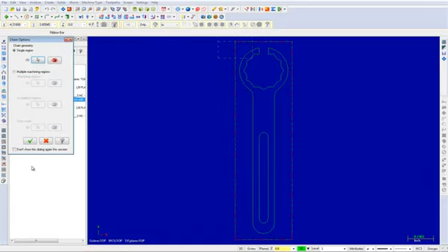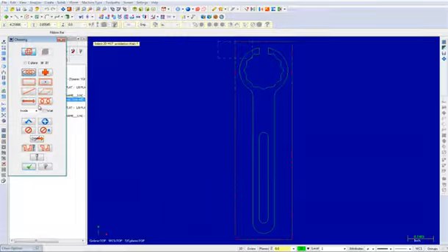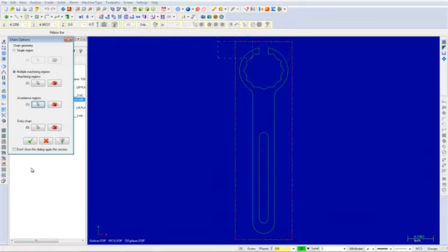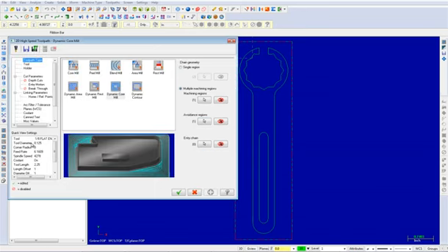In the Chain Options dialog box, enable the multiple machining regions. Now click on the Select button in the avoidance regions as shown. Select the following profile. Once complete, choose the OK button to exit the chaining dialog box. Again, select the OK button to exit the Chain Options dialog box. In the Toolpath Type page, select Dynamic Core Mill.